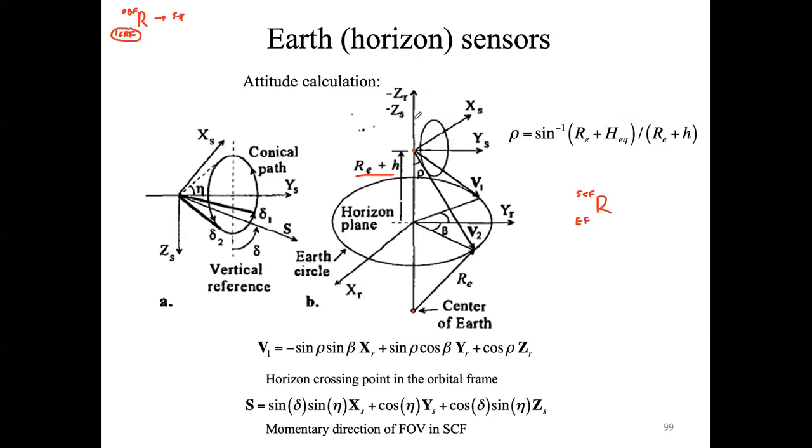So the two axes that you are defining are zeta r, basically along the radial distance of the spacecraft, but with a minus here, so it is minus zeta r, and yr, which can be considered as the pitch axis of the orbital reference frame. And now the problem that we want to solve here is to determine the crossing points of our scan, which is defined by this ring here, to the Earth disk. So this is the projection of the Earth disk as seen by the spacecraft.